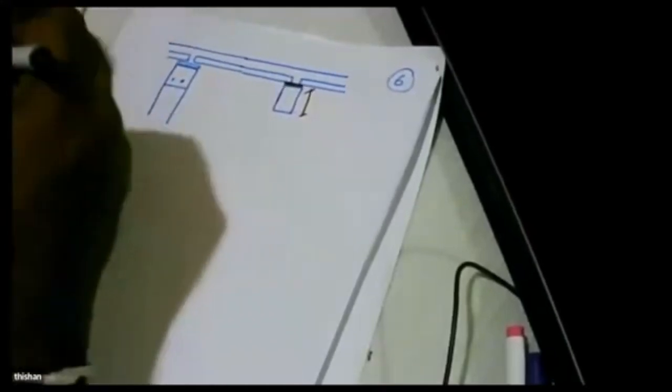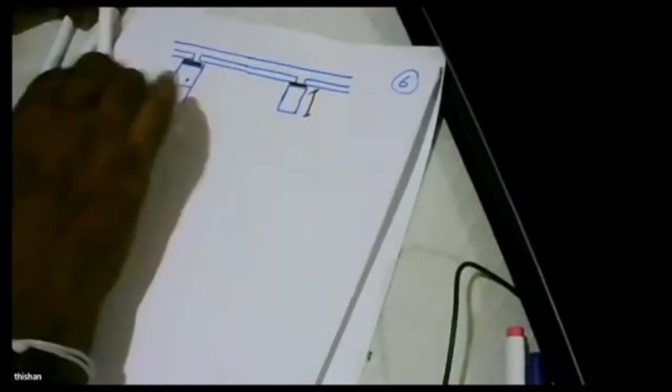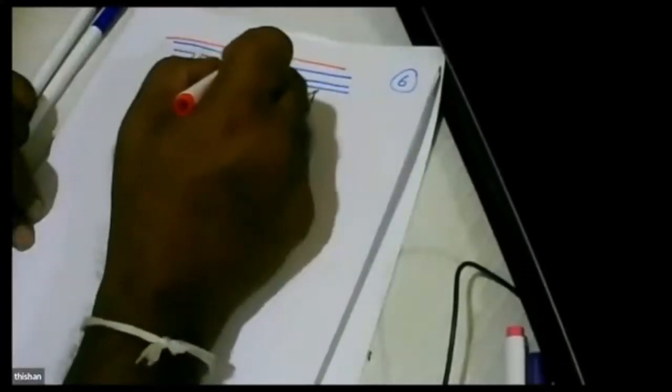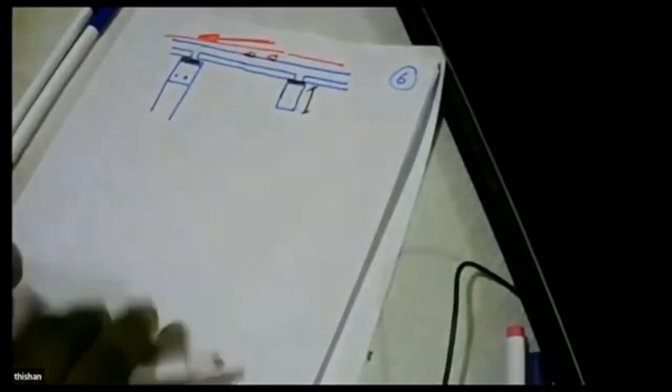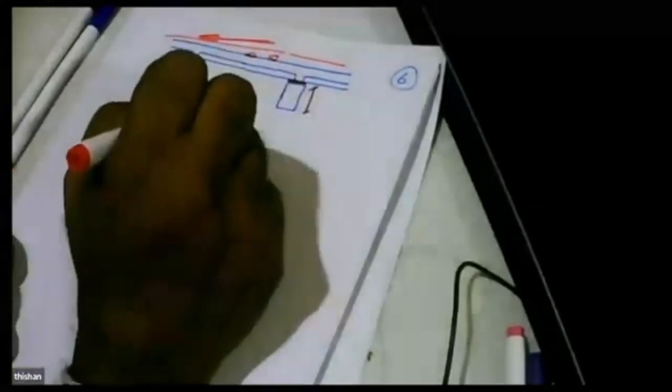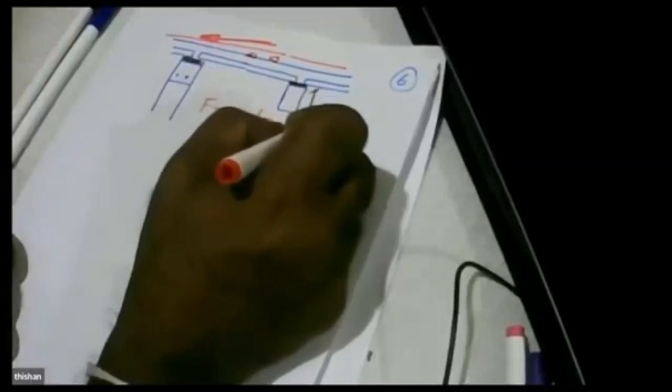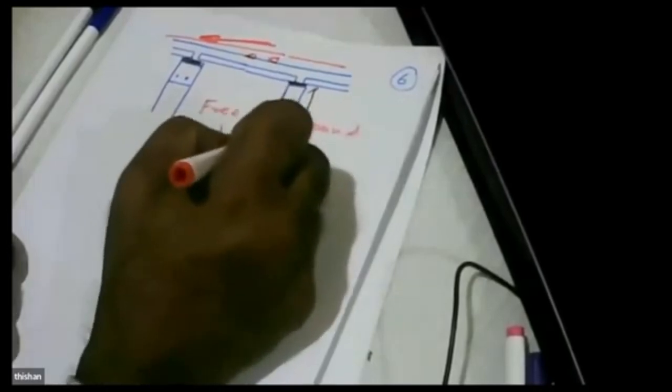So at all these locations we have a separation and a continuous slab, and we can make the concrete sloping as well. Don't have to do it flat. So we can drain easily as well. So we can have a slab which is free to expand and contract.